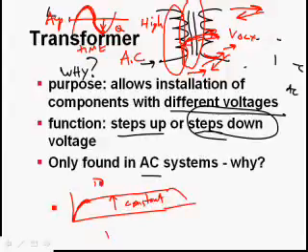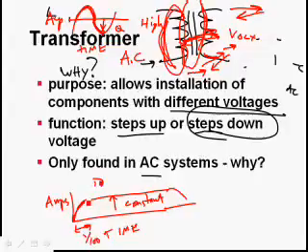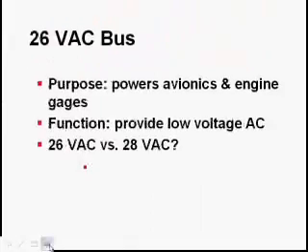And if we have constant amps over time, these lines of flux would expand to their maximum, and then they would just sit there. So we'd induce current flow for that thousandth of a second as the amps were increasing and as the lines of flux were crossing. But then after that, constant amps, the lines of flux won't move, no movement, no electromagnetic induction. So we need alternating current to have a transformer do any good.